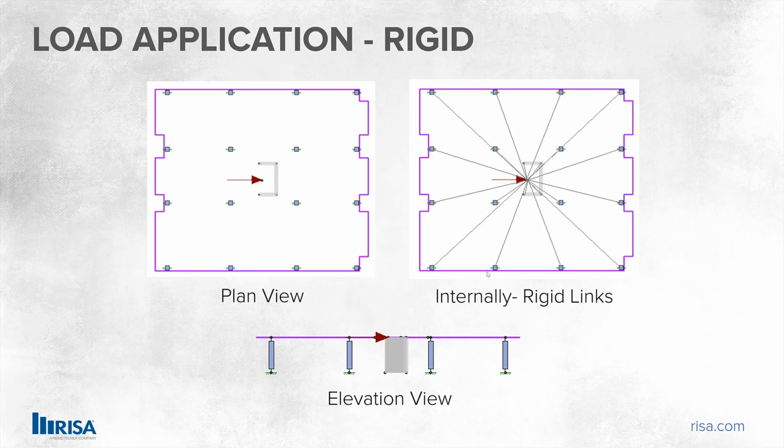In this case, the rigid diaphragms can be created independently in RISA-3D, without first having to tie the model into RISA-Floor, which we've done previously. Their definition is simply based on a selected node, which is then rigidly connected to every other node in the same plane as that node. So we don't have to use rigid diaphragms with RISA-Floor. We can do them separately just in RISA-3D, but in this case, we chose to set that in RISA-Floor and then transfer that over into RISA-3D.